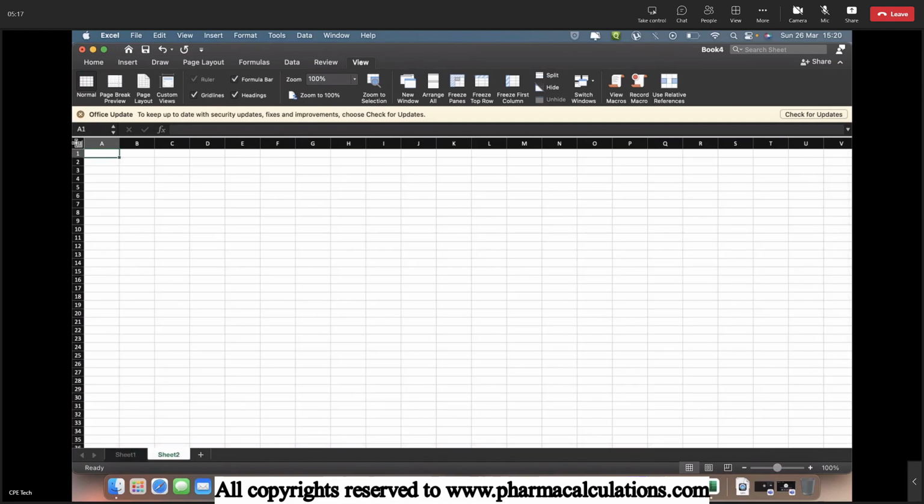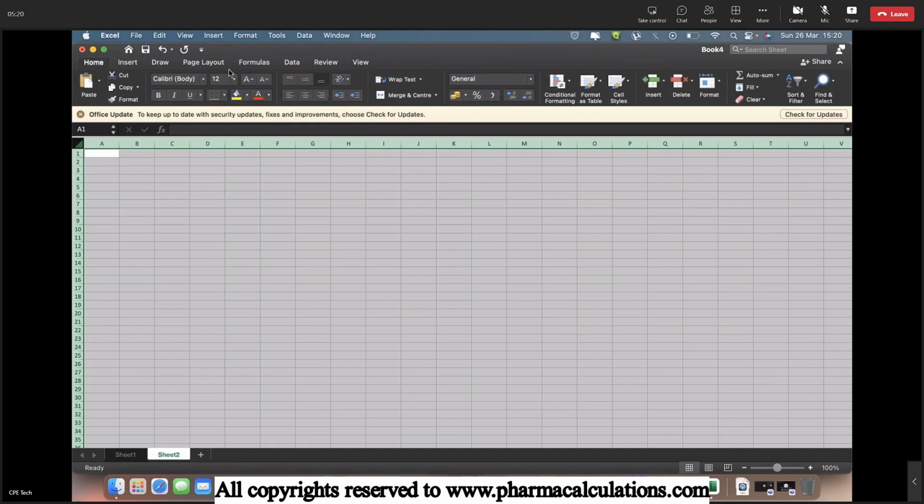Usually, you'll be having the regular utilities like RT water, chilled water, and chill brine, and the utility temperatures are going to be dependent on the operating temperatures. Like the chilled water is applicable only in the range of 10 to 30 degrees, and above 30 degrees we'll be using RT water. And if the process requirement is up to -10 or so, we'll be using the chill brine. And if we want to cool the reaction mass further, or if we want to perform any operation beyond -20 degrees of temperature range, we'll be going with liquid nitrogen.